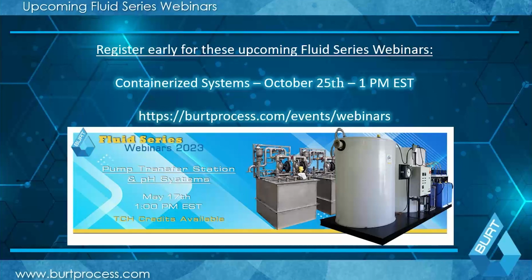Do you have to always assume 100%? Not necessarily. In the example I showed, it was a relatively simplistic one. There is a little bit of give and take. If you can end up with a very high flow rate, then you may end up with somewhere close to maybe a 70% diversity factor. So you cut it down a little bit, but not to the level where you'd say my worst case flow rate is 5 gallons a minute, where they could have 25 gallons a minute. There are different schools of thought on that. The sizing I'm giving here is probably a little more conservative.